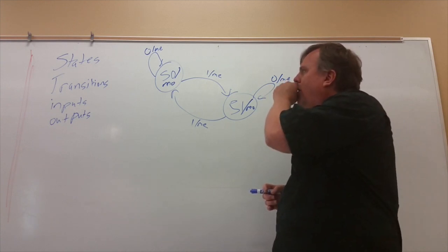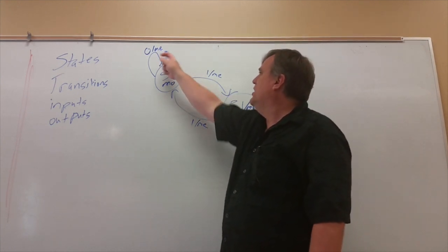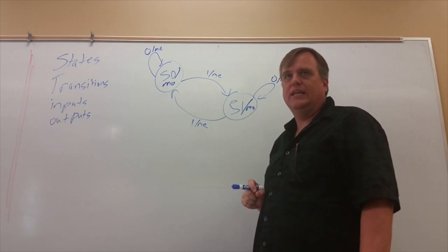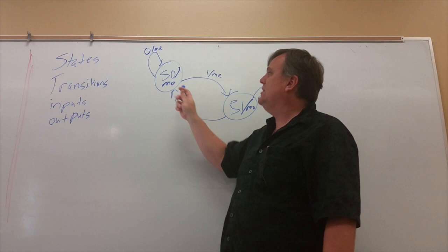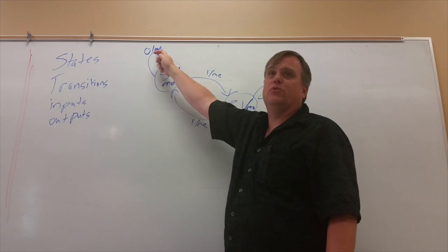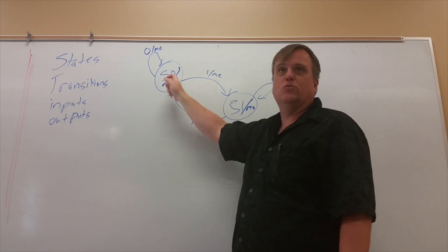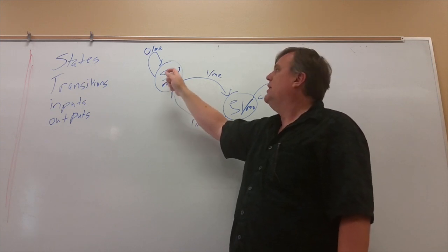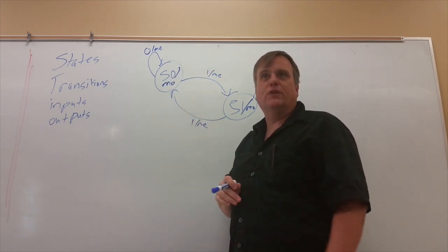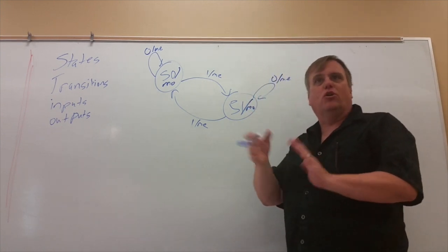Technically speaking, I said it could be up to twice as big. But imagine every one of these Mealy outputs was different, all different from each other, nothing in common on any of them. Then theoretically, in this case, I would need twice as many states. Because I would need a Moore state to handle that output, and I'd need a Moore state to handle this output. So I'd need 2 for this one. I'd have to split this one into S0 that's staying and S0 that's going. So I could handle the 2 different outputs and just clock them. Right? And because I therefore have those, it's going to be slower on the transitions.